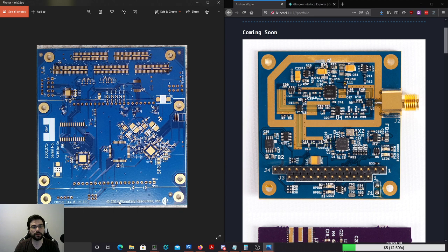And the reason we didn't catch that, we ran a test. We were like, hey, we got to make sure that we have our numbers right. But the person who ran the test was an intern, and they tried to do low side sensing. So they sensed the current through the ground lead instead of the power lead, which would be fine, but you have to really nail down that you only have one ground connection. And he had a second ground connection that he didn't notice through the FTDI cable that was connected for communication. So, bada bing, bada boom, he measured 5 watts, which is what he expected to find, because we had papers and case reports that said, hey, it's 5 watts. No, it's 15 watts. And this right here basically doomed that mission.